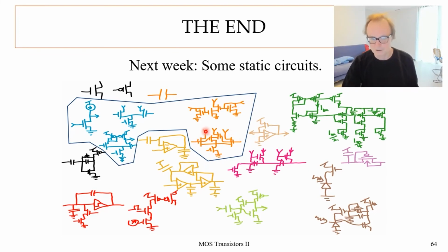Interesting circuit. And perhaps she'll start working on things like the current mirror that copies a current from one branch to another, and that is used together with a diff pair to make the simplest transconductance amplifier that takes a difference of voltages and turns it into a difference of current that's scaled by your desired tail current or your bias current.